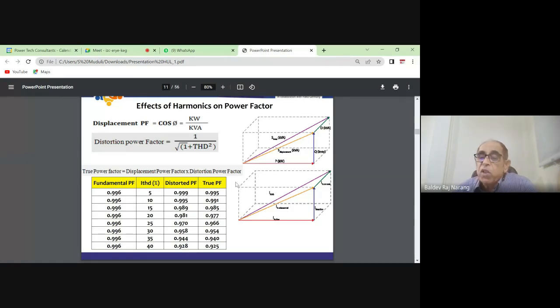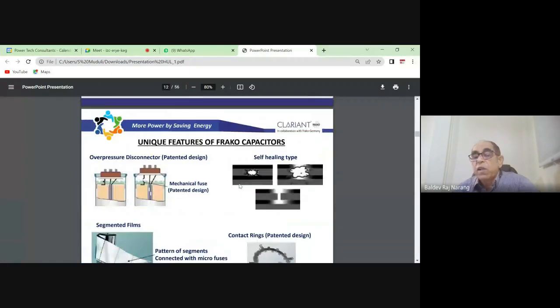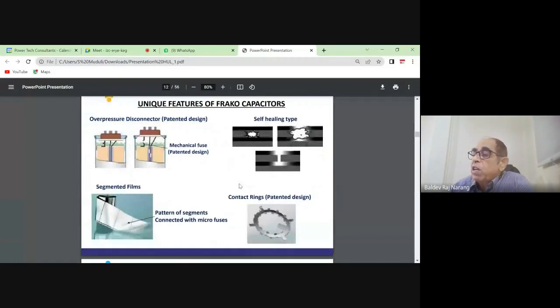We have seen the effect of leading power factor, but we can see the effect of harmonics also. Normally we are never going to have this 40%, except maybe in some exceptional cases where some industries may have problems and issues. And they are not allowed to have that much harmonics, because penalties and other things will not allow you to go there. But normally we have 10%, 15%, and it is always marginally affecting.